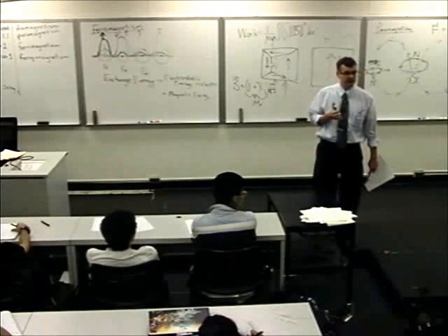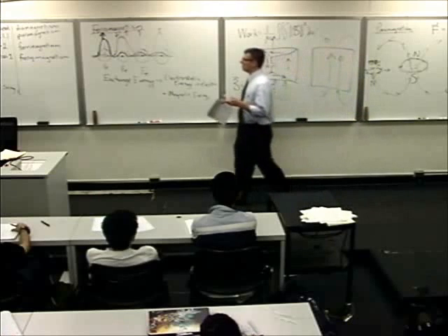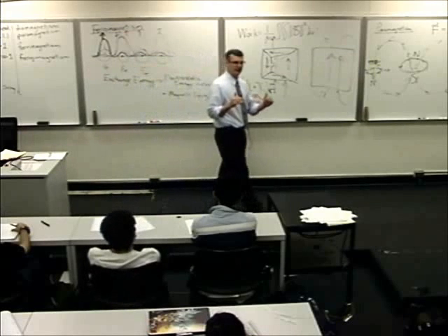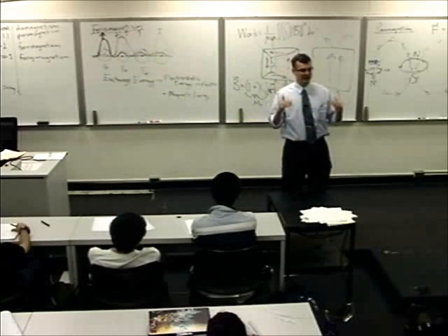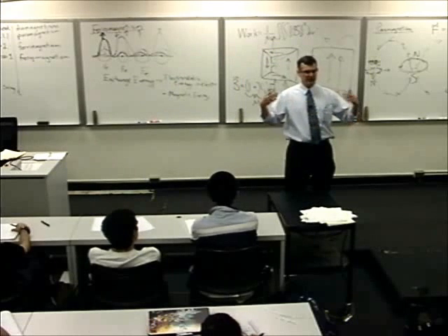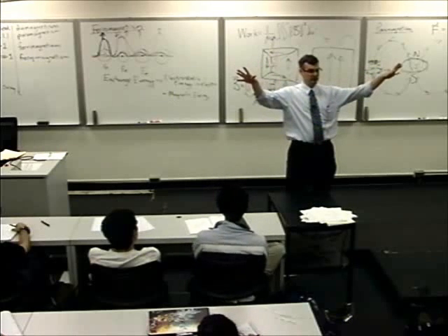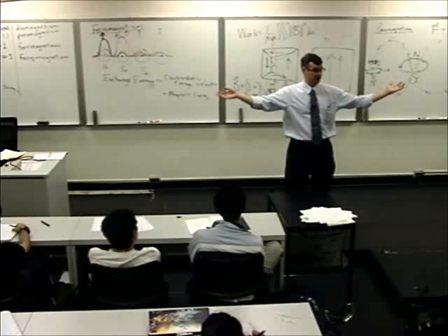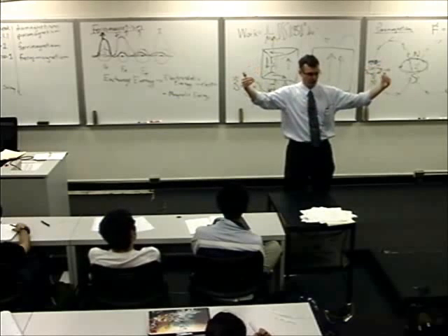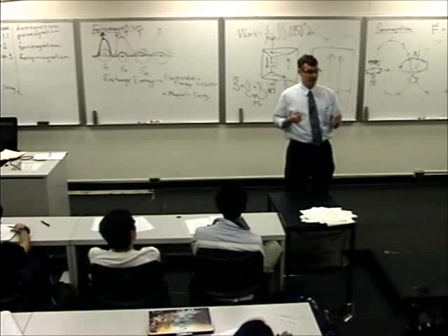Yeah? So what are they doing with the supercooled magnet? Oh, yeah. One of the reasons why iron magnets get all the publicity is that it's one of the few materials that operates at room temperature below its Curie temperature. The Curie temperature of a magnet is the temperature past which, once you heat it up, the exchange energy goes to 0 or less, and you lose the cooperative ability between the atoms. Well, it turns out there's a lot of magnetic materials that exhibit ferromagnetism, but at room temperature they are above their Curie temperature. So if you supercool them, they drop below the Curie temperature, they start cooperating with one another, and you get these powerful magnets that form.